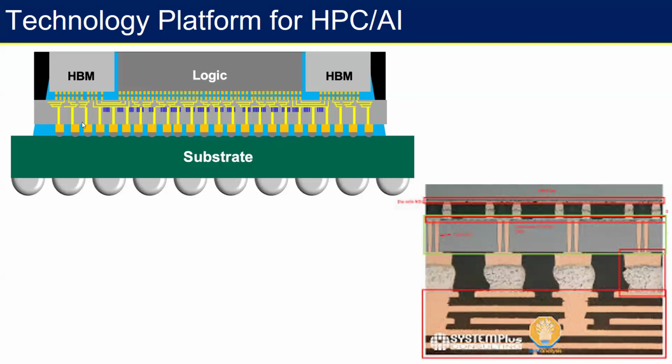Which is what connects. And what are these orange and the dark gray portions? Again, these are called micro bumps, because they are not as big as the bottommost solder bumps, but are smaller in size, and that's why they look the way they look, right? And this you can see from the picture, which is directly a TEM cross section from a die, where you see these big things, which are your, let's say, bumps, while you see the smaller ones, right, which are your micro bumps, which you are connecting.